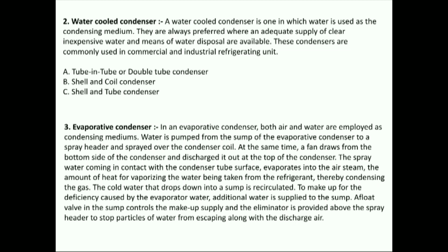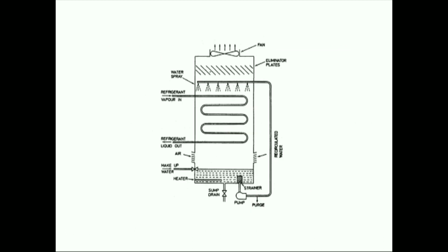Additional water is supplied to the sump. A float valve in the sump controls the makeup supply, and the eliminator is provided above the spray header to stop particles of water from escaping along with the discharge air. Cooling tower.